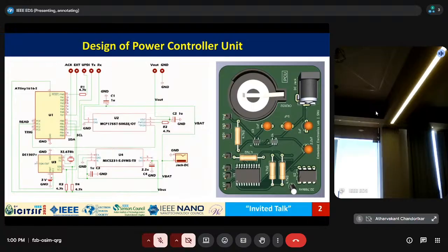So you require another regulator IC which supports high current. It supports up to 300 milliampere load current, but for its internal operations it will consume 3.5 milliampere. So we have to think about whether any other low dropout voltage regulator IC is present in the market which consumes less continuous current and gives high current output. That's why I'm saying that at maximum we can optimize it to 5 milliampere.